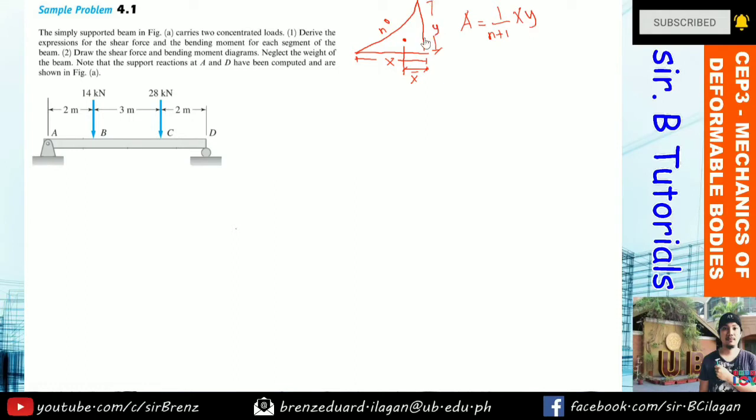So try natin sa triangle, di ba? Kapag triangle, first degree siya. So ang n mo mapapalitan lang ng 1, or the area is 1/2 of x times y, or the base times height. And yung pagkuha ng x bar natin coming from the maximum height o yung highest point ng isang curve, ito. So ang distance mo is away from that. So that is equals lang sa x all over n plus 2.